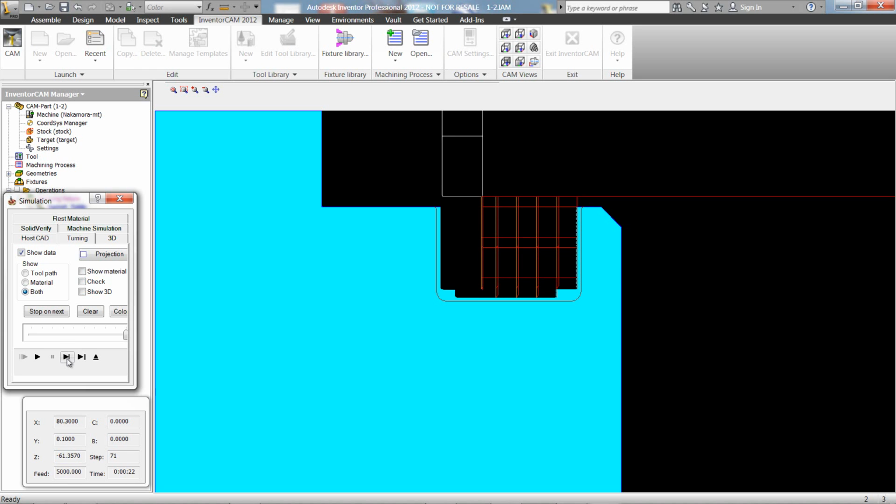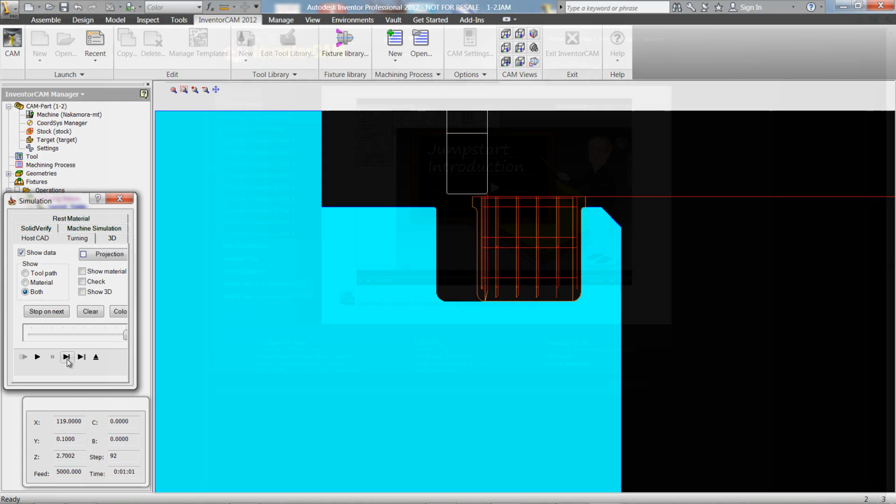Now it'll start to finish. The finish, it'll go down, then back up, get the corner, get that bottom corner, and now it'll move across on the bottom. That's what the advanced keep down does. Now it'll move back up, go back to the side, finish off that edge over there towards the bottom, and now work its way out of the groove.